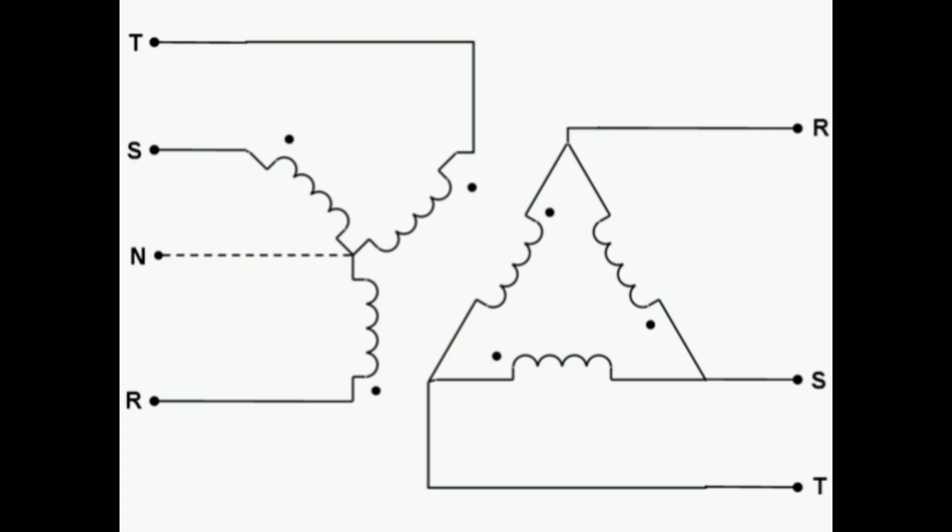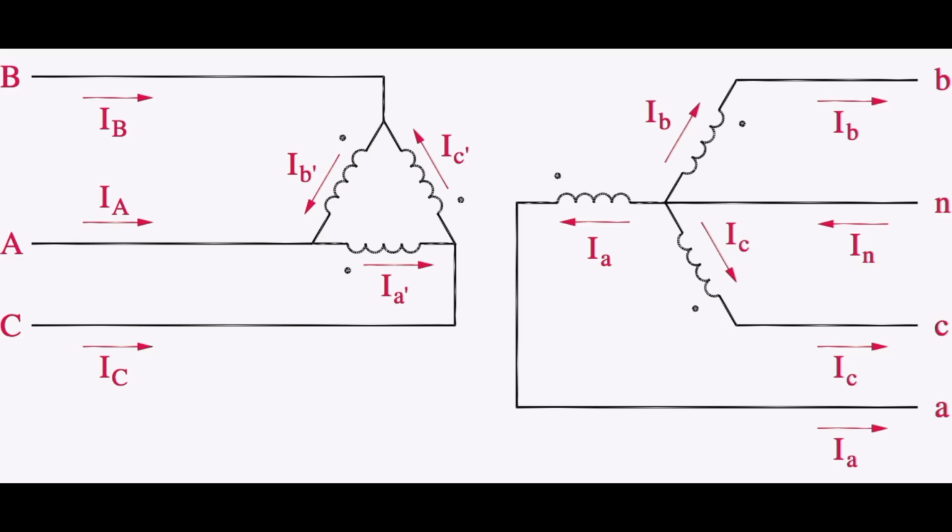The second importance brought about by delta is higher fault tolerance. Here it can withstand single-phase faults, for example a short circuit, in one winding without affecting the other windings, making them suitable for applications where fault tolerance is important. Delta-connected transformers are commonly used in industrial settings, especially where the load is typically unbalanced and where the system size is relatively small.